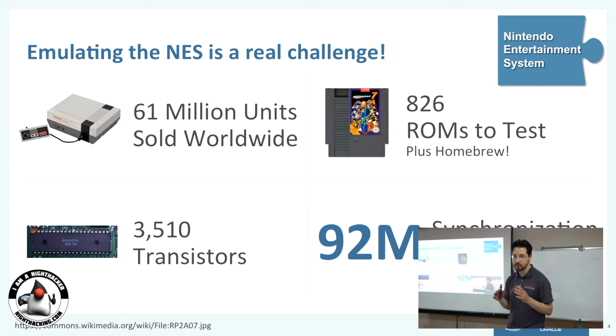So one of the challenges with doing video game emulation is to get the precise behavior of these old chips with the timings. So there was a CPU, there was a graphics processing unit, or a pixel processing unit. They call it a PPU. And there was an audio processing unit, an APU. And these three chips had different timings.